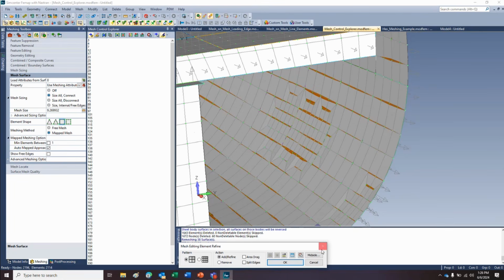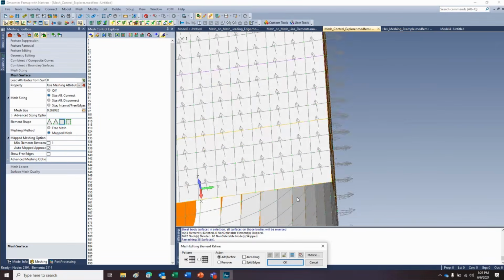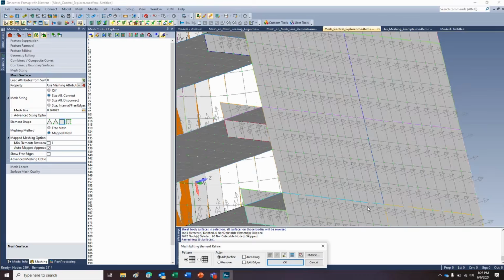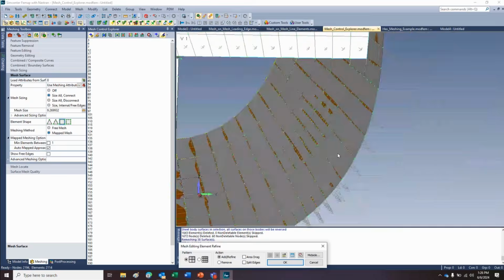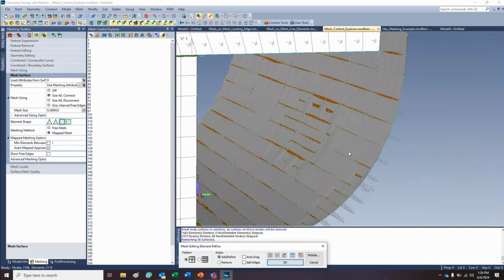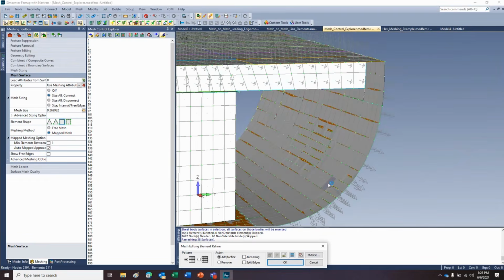Any loads on the elements get split on the elements. It all gets composited, it's all done. Directions get propagated. Constraints would actually get split and propagated. Are those nodes being pushed to the surface? It's not just splitting the elements. If there's a surface geometry there, then they're going to be put on it. Okay, so those are going to surface.